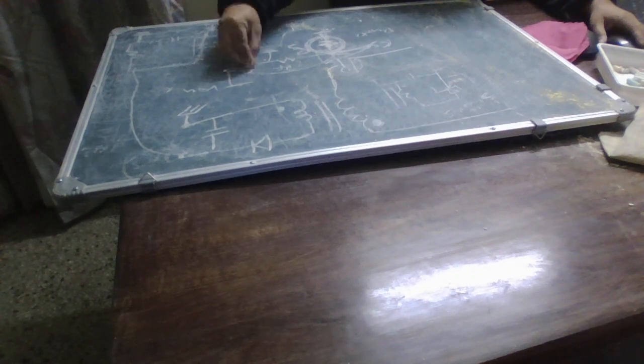So we are first calculating the maximum current sense resistor value, assuming we are not using the external slope compensation. So this is 0 ohms here, and then we can calculate the maximum value of this current sense resistor.